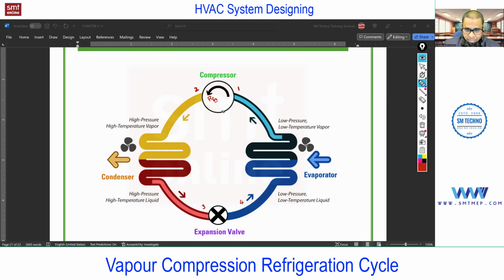And when you switch on the compressor, how can we switch it on? By supplying electrical energy. For example, when you plug in, or when you supply electrical energy, the compressor starts. You may find different types of compressor, like centrifugal, reciprocating, etc., which we'll discuss later at the time of classification of machines. At this level, you know what the compressor is? The compressor is used to compress the refrigerant in the gas state.